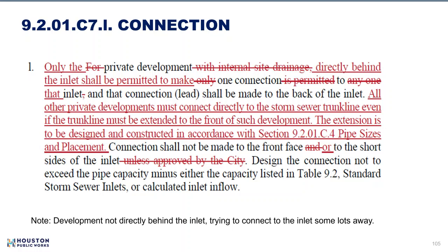Because if you do that, you have a 24 inch pipe in the storm sewer, in front of the property line and behind the curb. When you have this 24 inch storm sewer pipe going through the neighbor's property, and the neighbor redevelops and tries to connect the storm or especially the sanitary sewer, they will not have enough space, and they won't be able to cross your designed storm sewer pipe.